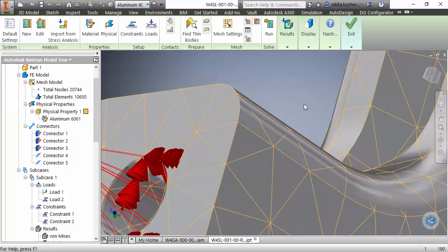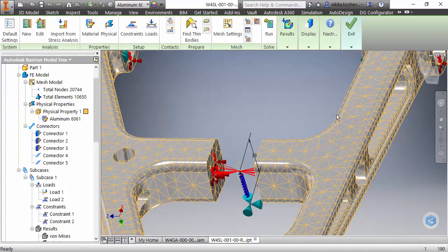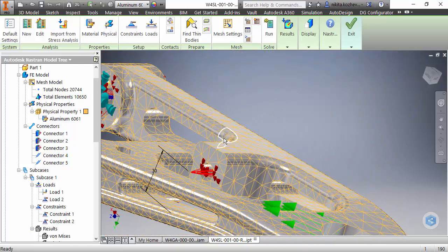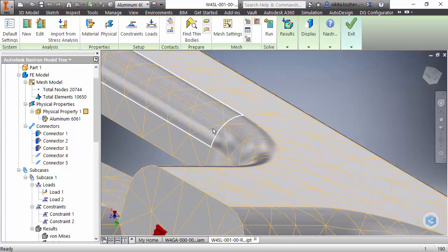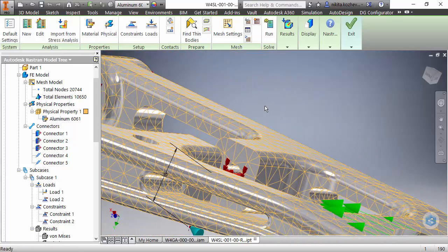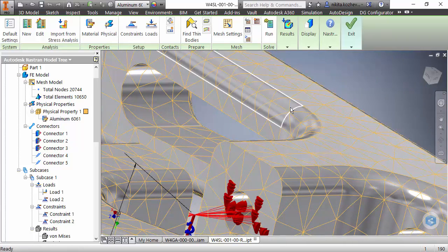Also, in order to make sure that the result around the stress concentrator is correct, we need to do a mesh convergence study. Sometimes big elements or a rough mesh do not have enough resolution to compute the load factors with the required accuracy.